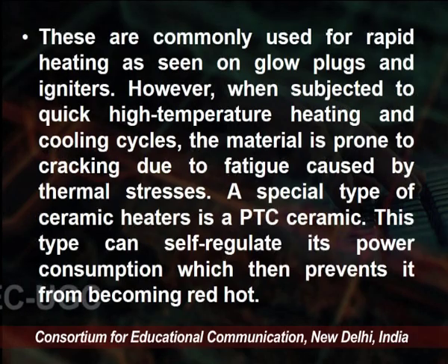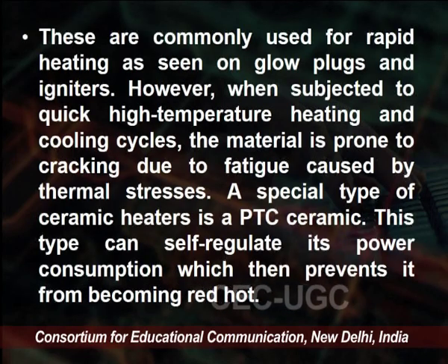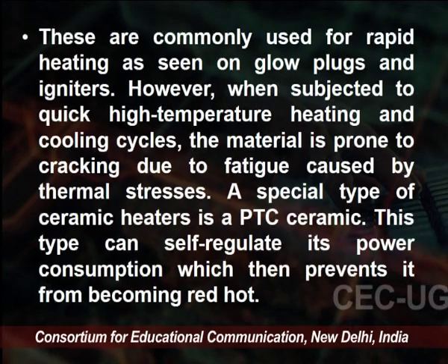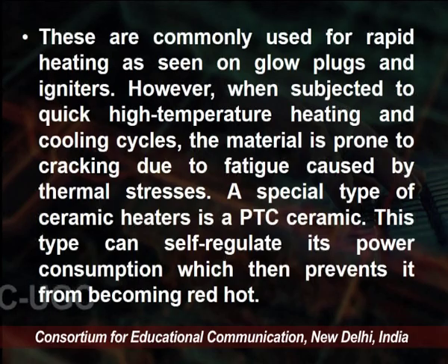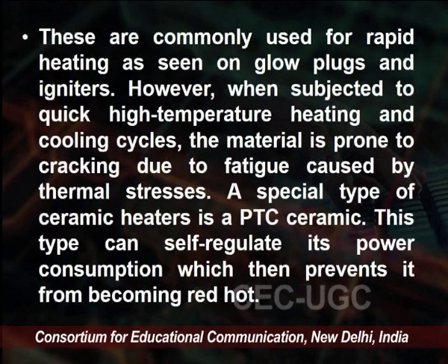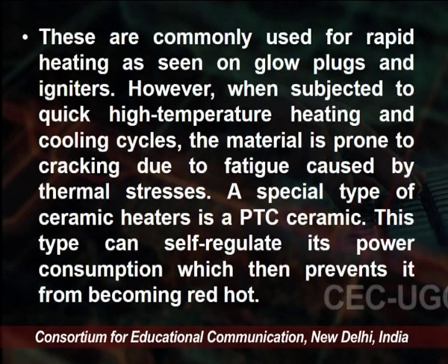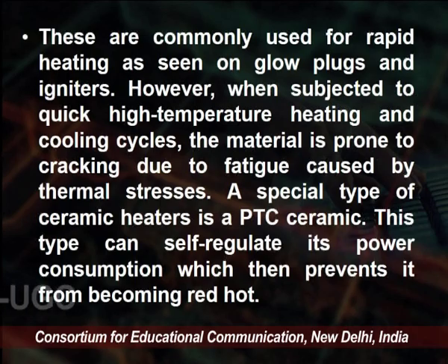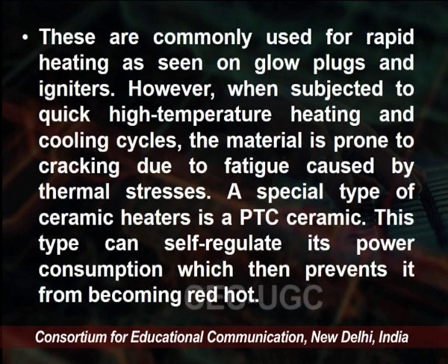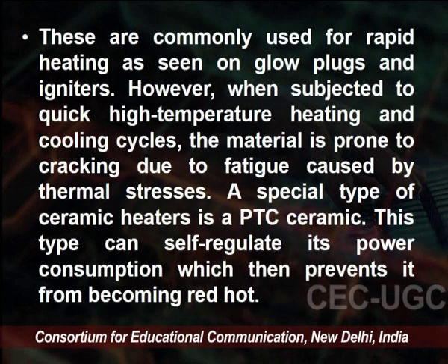So when subjected to quick high temperature heating and cooling cycles, the material is prone to cracking due to the fatigue caused by thermal stresses. So a particular temperature should be maintained for this type of heater. A special type of ceramic heater is the PTC ceramic, and this type can self-regulate its power consumption, which then prevents it from becoming red hot.